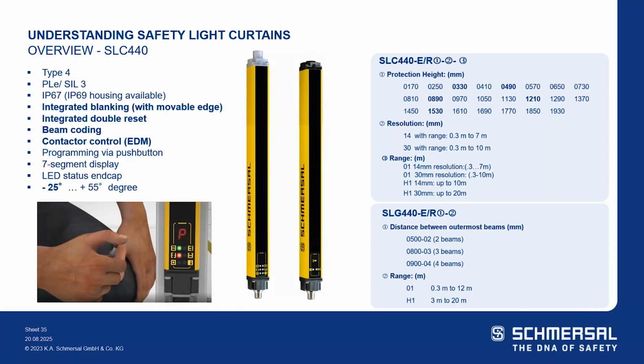Then you move to the SLC, the full featured SLC 440 series. So here's your type 4 light curtain SLC or light grid SLG, performance level E, SIL 3, IP67 with IP69 housings available. But now, more than just your on-off, now you've included your integrated blanking, fixed floating, and floating with fixed with movable edge detection, integrated double reset built into the unit, beam coding.